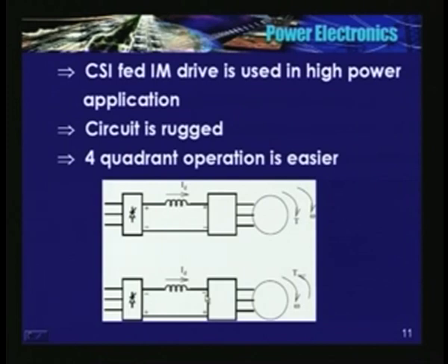Now we want to go to second quadrant or fourth, depends on which one you have taken, T along x axis or y axis, it does not matter. So what do I need to do? I have to interchange the polarities here by increasing alpha above 90. Of course, current direction is the same. You cannot reverse the direction of current.